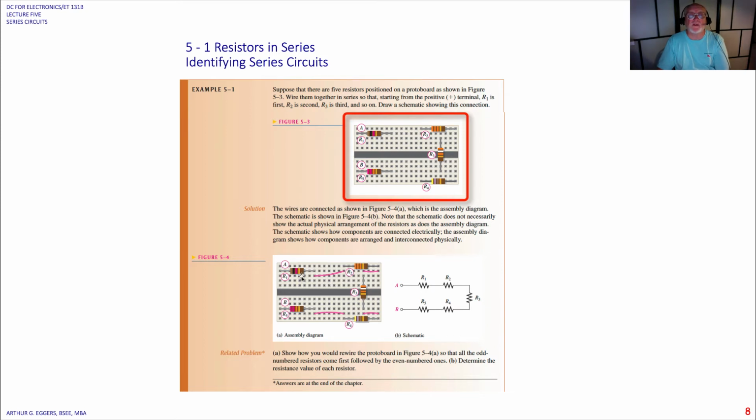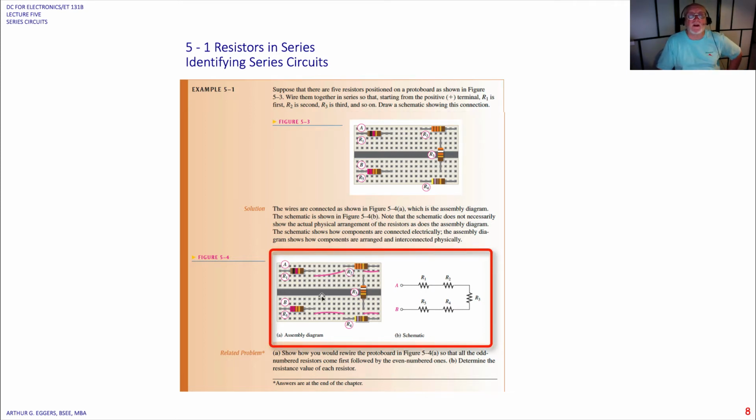So as we go through here, now we need to learn about what's going on a protoboard. On a protoboard, any of these vertical points on here are connected together. So when you plug a jumper wire in this hole and plug it into this hole, it becomes a series path. So you notice here that as we're going along, we create each of the paths here by plugging into the correct hole in the protoboard. And so out the other end, our total resistance actually is across A and B when we connect all 5 of these resistors together.